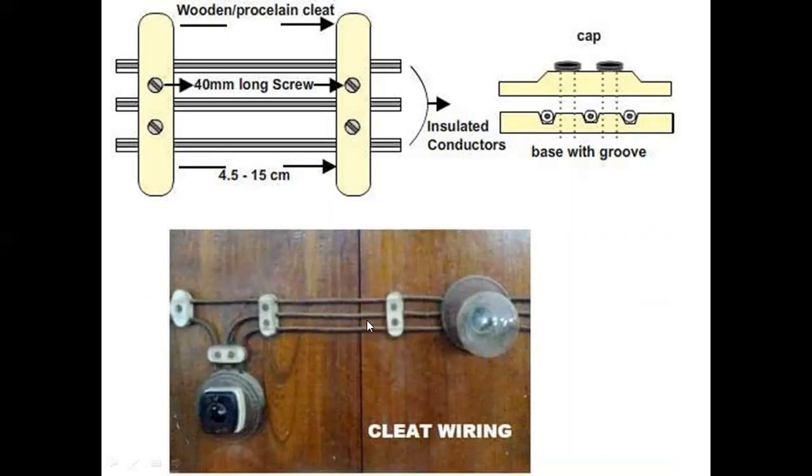So that's why it is most dangerous, because if any fire hazard happens, then this wire is not suitable from the safety point of view. That's why this should not be used as a permanent type of wiring. It's just temporary. You can use it for one day or any function or marriage, and on the same day you can remove all the cleats.